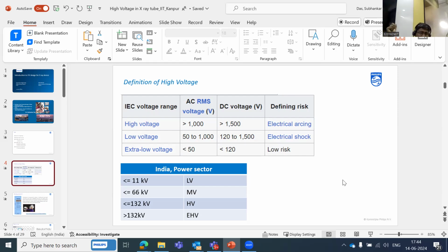Before even applying the high voltage, a command comes from the device, which we call preparation, and it pumps a boost current first, which is a very high current for a few microseconds, and then falls down to a current which quickly takes the temperature to that. So the boost current is to take the temperature quickly to 1800 degrees centigrade, and then the high voltage exposure.